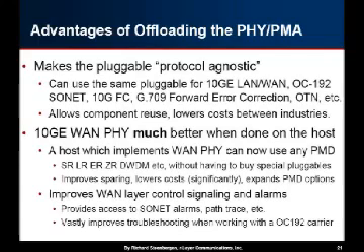and you can even use it in transport networks that are doing forward error correction. I think Juniper announced a few days ago that they are now doing forward error correction framing off of their 10 gig PICs on T-Series. So that will let you, for example, potentially take what used to be an 80 kilometer optic and now maybe get 120 kilometers out of it just by a little bit of software coding. So it's great technology, and being flexible and being able to implement that on the framer without having to upgrade your optics, or to be able to implement different versions of FEC, is a good thing.